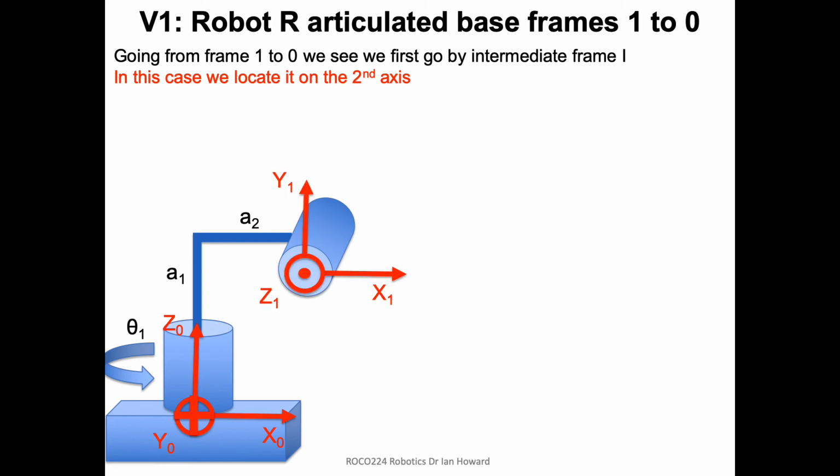We're going to have, basically for this particular link, this is what we end up wanting. We want to know where this is located. Where is the frame located that is then around the second joint, right? Because this is a rotary joint that will normally go on to another part of the robot, this is going to be the z-axis along here. In fact, it's actually coming at us, right?